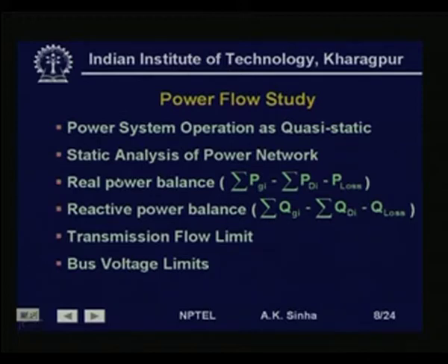Okay, so now we will start with power flow study, what we really are trying to do in this study. As we said, we are considering the power system operation as quasi static. Therefore, power flow study is basically a static network analysis for a power network.